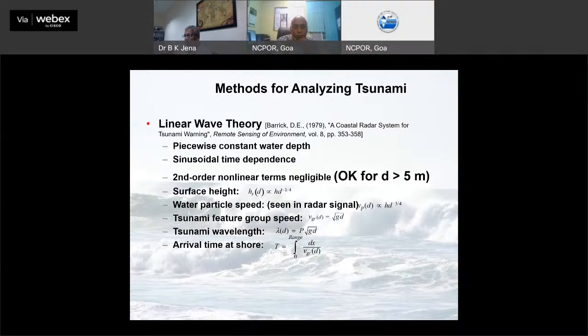When a tsunami is arriving at the coverage of the radar, the current speed will reduce drastically. So that will give a signal to our central sites, and with that we will alert and see whether the signal is false or right. Accordingly, we can also check it with INCOIS, and this data is also given online to INCOIS. They can correlate with the BPR and other systems whether it is right or wrong before giving out the warning.